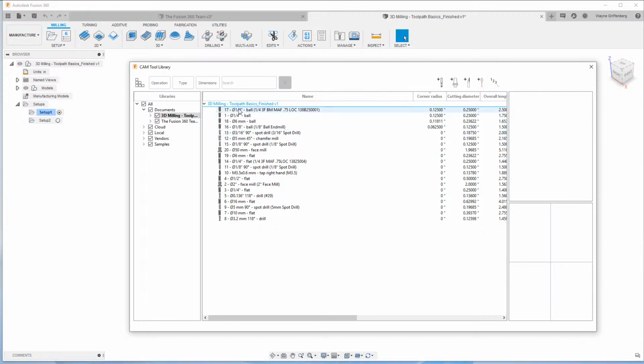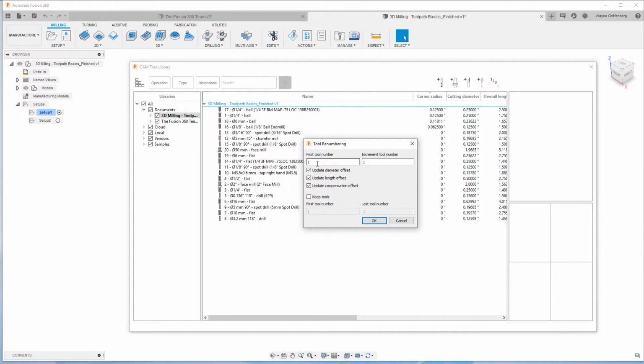So now let's say in one machine, I used to use this. We used to have a multiple head router, Heian routers, and they had 4 main routers and 2 piggybacks. And there were specific tools that we could use for the offsets because the main head routers used to have different offsets. So you couldn't put those same tools in one head and another, or else you would crash, or you'd have to make multiple duplicate libraries. So what we used to do is we used to number them. So for all tools in head number 1, I would say start with 101 to 151, or let's say tool number 150. So we'd have 49 tools, right, or 50 tools.